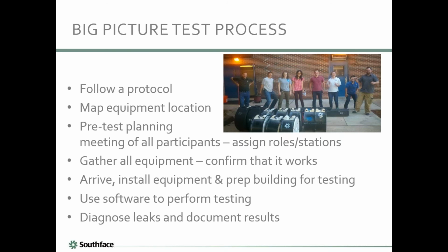When people were assigned to a location, they would set up the equipment or do whatever. Once we were doing the test, part of their job was to find problem areas in that zone. And I guess that's a good point to say this type of testing can be done to get a specific number at a specific reference point to show that you pass a standard, but it's also a great diagnostic tool. If you're out there trying to solve comfort issues and energy issues in a building, this type of testing can really be done purely for diagnostic purposes. Where are the leak pathways, and what can we learn from depressurizing or pressurizing the building and investigating?